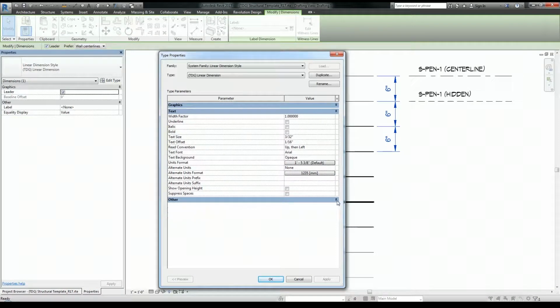In a previous tutorial, I set up my font styles, and unfortunately Revit doesn't have the option to use the font styles that I created previously. So I'm going to have to recreate those font styles here so that my font is consistent throughout my Revit styles. So this first option here is the width factor, and I recall my font style settings, and my width factor was 0.8. The underline option was left unchecked. The italic option was also left unchecked, as well as the bold option.